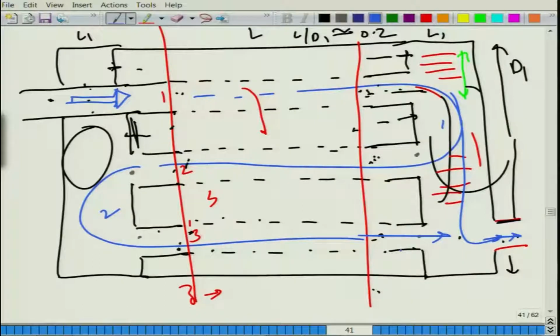So, basically the waves have multiple paths through which they can go. This is just one motivation for why we study multiply connected mufflers. You can synthesize a number of configurations in which the wave propagation path is non-unique.